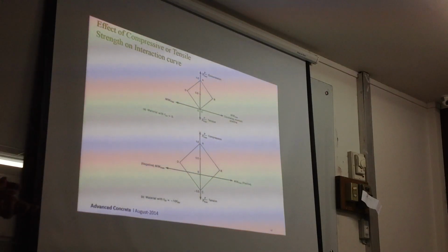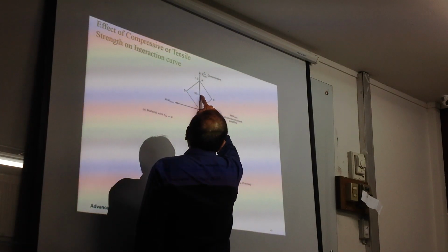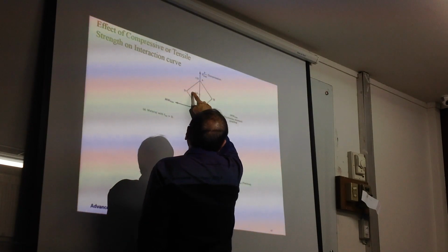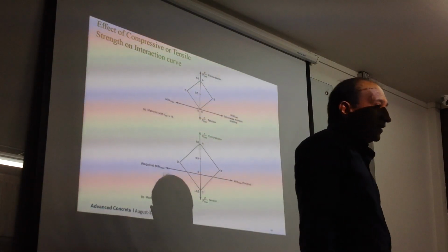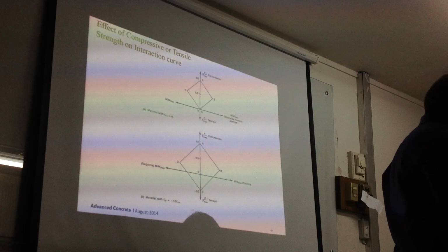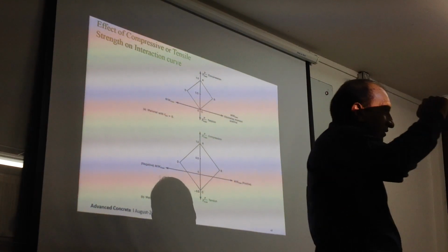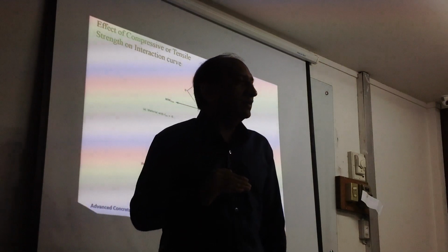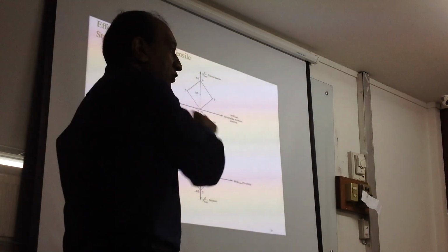At some point you will reach maximum moment with about half, let's say, load capacity, right? After you cross that, moment will start to decrease again, right? So that is why we cannot take the maximum P and maximum M and design for it. We need to design for all of them because we don't know what the ratio is.